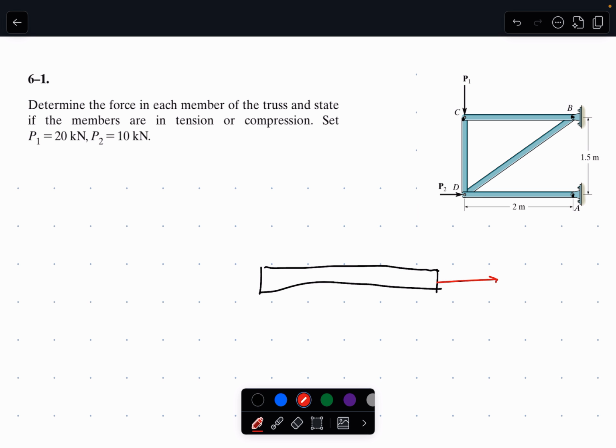So what tension is, we've got two equal forces pulling the beam apart like that. Okay, and if the force deforms the beam any, it'll stretch out like that. Okay, it'll get skinnier and longer, I should say. And then compression is the opposite. You've got two forces pushing the beam together, and if the beam deforms, it should get a little shorter and a little thicker like that.